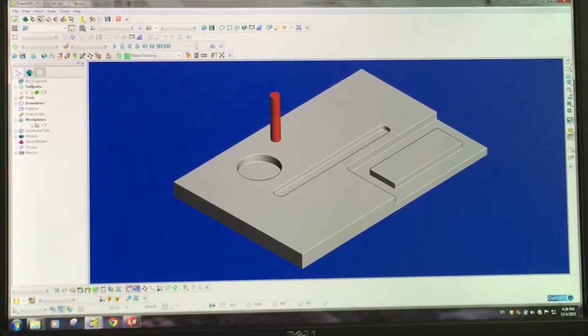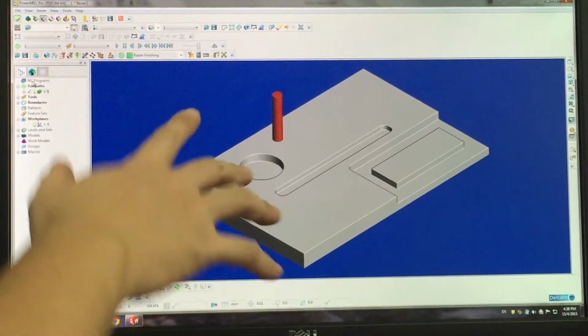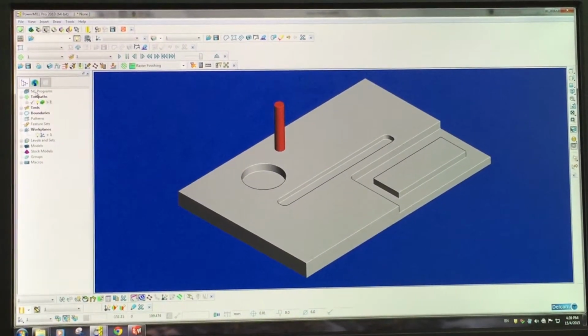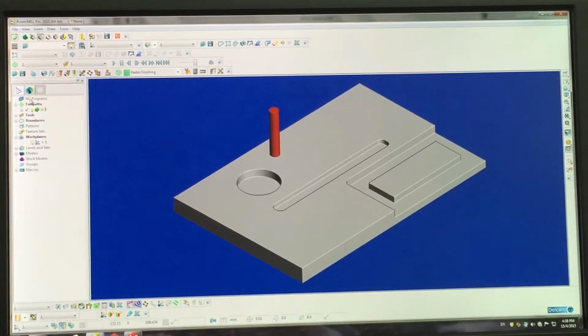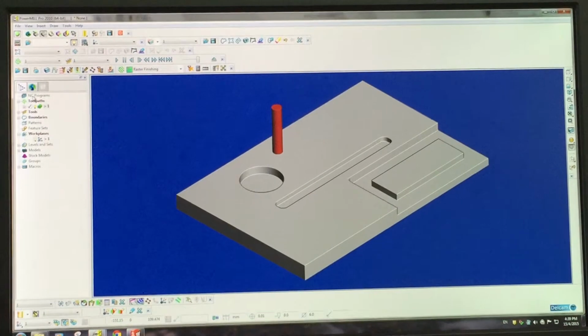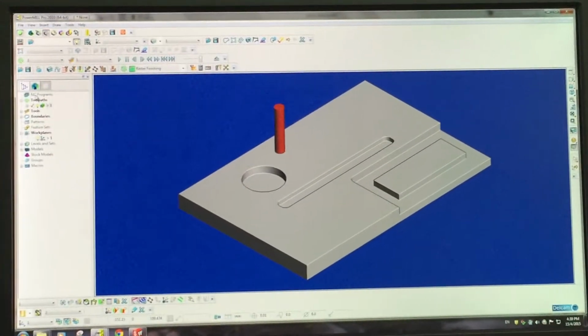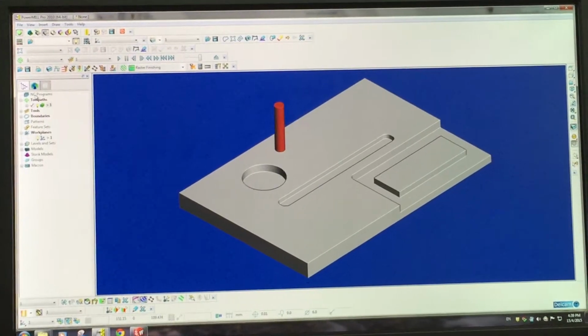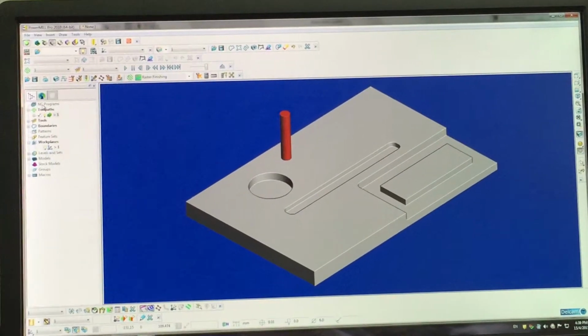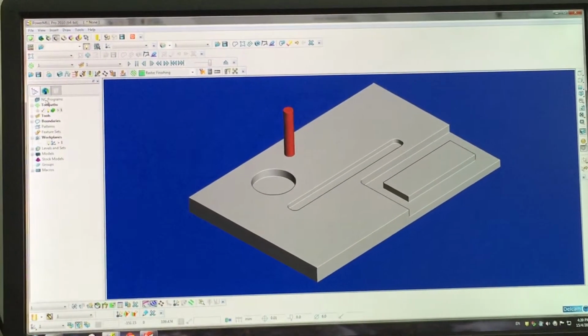Okay, now we've completed the simulation. Did Olive actually mention to you about saving the file from SolidWorks? Oh yeah, the IGS. Make sure you save in IGS format. Of course, you can also save one in the SolidWorks part format just for your reference in case you need to do editing.